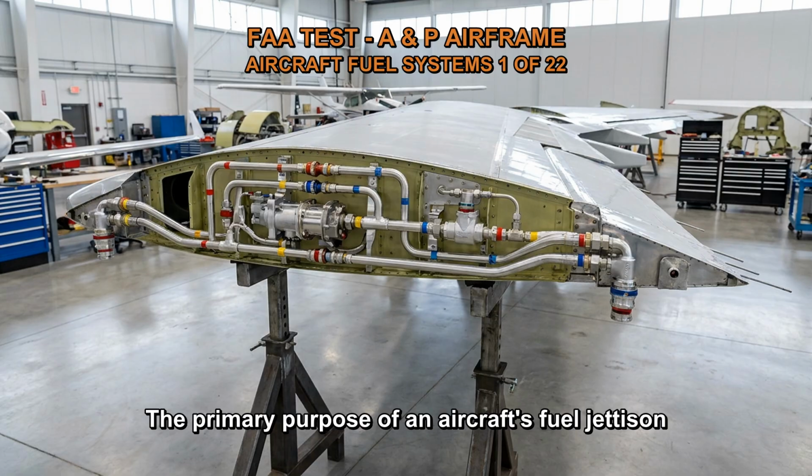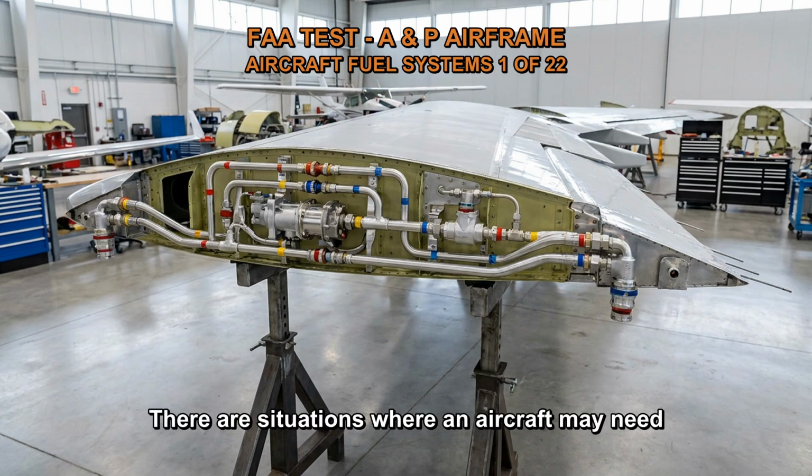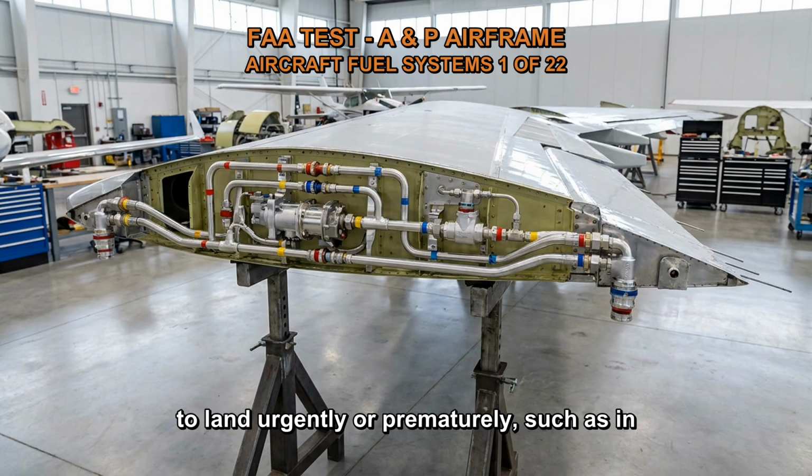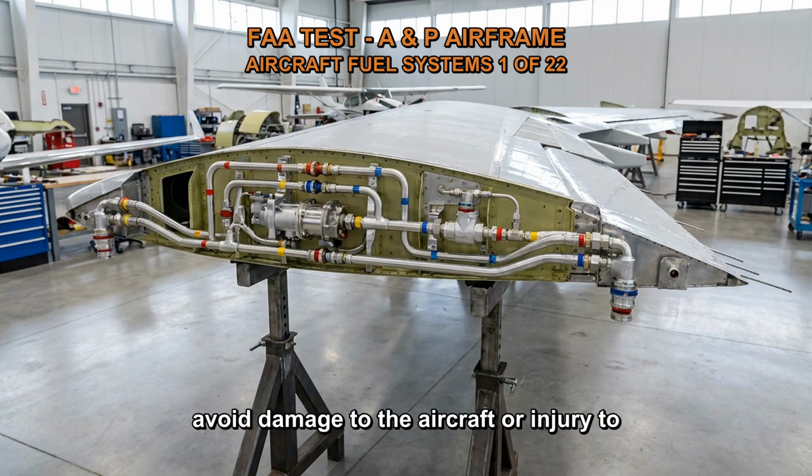The primary purpose of an aircraft's fuel jettison system is to quickly achieve a lower landing weight. There are situations where an aircraft may need to land urgently or prematurely, such as in an emergency or when a critical system has failed. In such cases, the aircraft may be too heavy to land safely, and it may need to reduce its weight rapidly in order to avoid damage to the aircraft or injury to the passengers.